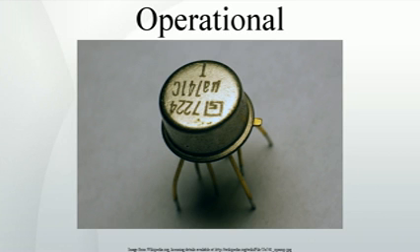Operation. The amplifier's differential inputs consist of a non-inverting input, +, with voltage V+, and an inverting input, -, with voltage V-. Ideally the op-amp amplifies only the difference in voltage between the two, which is called the differential input voltage. The output voltage of the op-amp Vout is given by the equation, where AOL is the open-loop gain of the amplifier. The term open loop refers to the absence of a feedback loop from the output to the input.